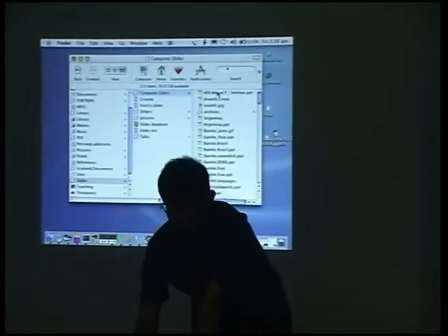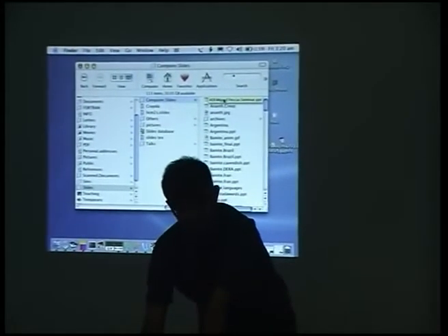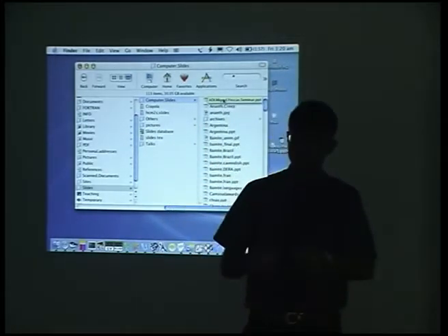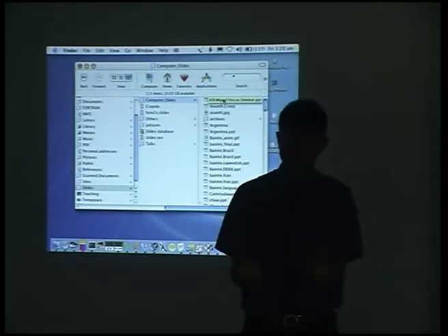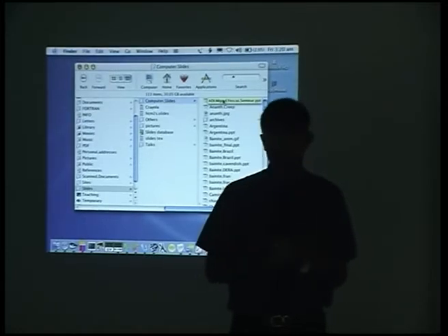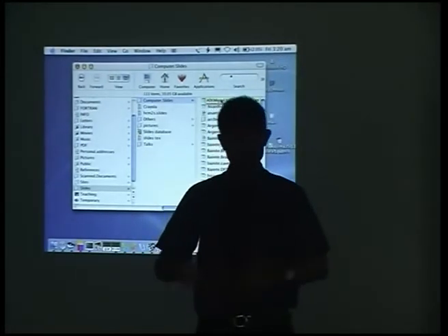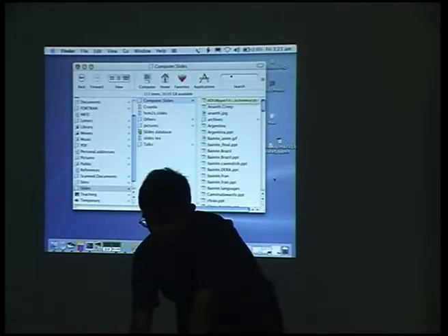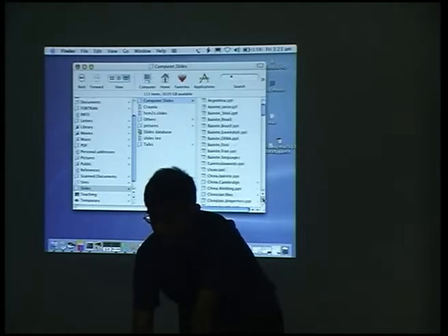And show you, people think that we can improve toughness by adding nickel to a ferritic steel. You find it in many textbooks and so forth. So we were asked to develop a welding consumable for submarines, which can be used without any preheat and so forth. That's a really tall order. So of course we thought, okay, the first thing to do is to increase the nickel concentration. And after 3 years of work, it didn't actually succeed until we did a neural network model.